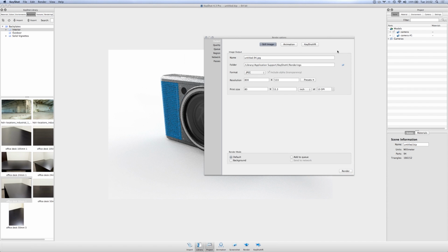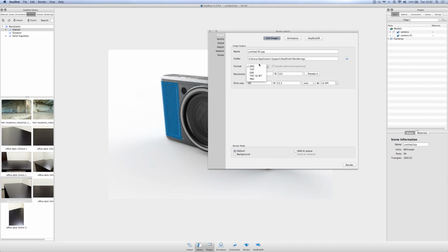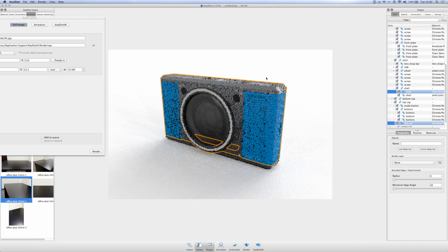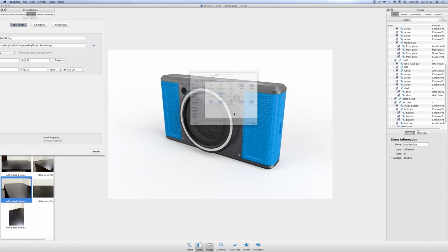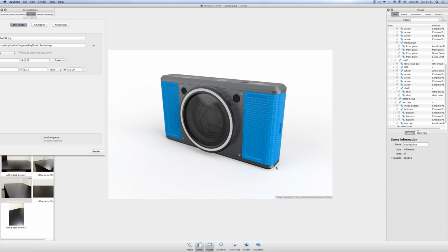So in this case, we're not going to get into animation in VR, but what about actual render output, right? So we've got a couple different file formats that we could render to. Let's say we're not working with a full-on rendering that's got to go to print or anything like that. I'm just rotating my environment, holding down Command on the Mac and Control on the Windows side. But if we let this sit here just for a couple of seconds, you can always hit the screenshot button, and that'll save out a screenshot of whatever is on screen. In this case, it's going to pop up and ask me, and I'll call this my camera 1, and I'll save that just as a PNG, right? So I can always go back and just have these screenshots.